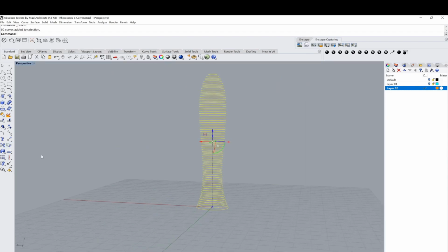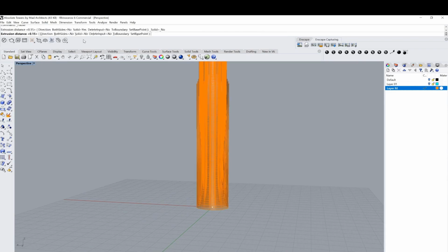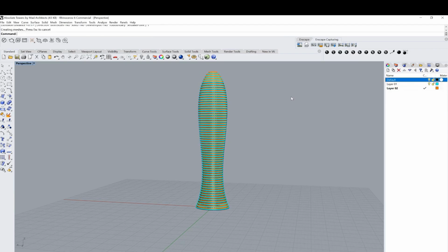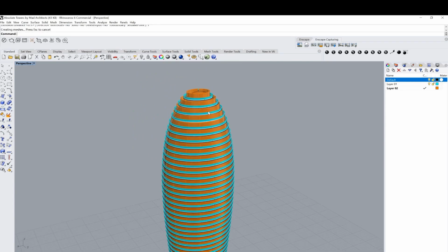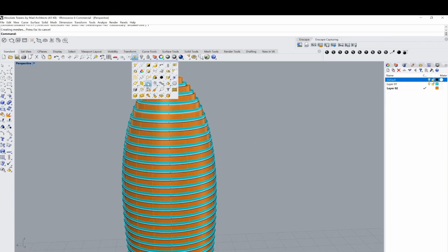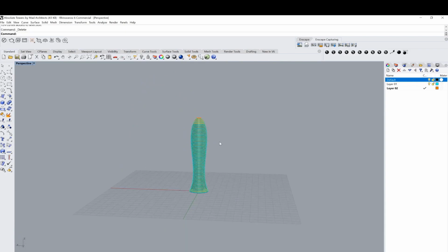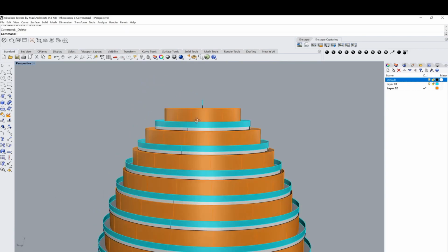And then we extrude curve. Extrude straight. Check your solid option is off because we are only creating our glazing, right? Not solid forms. So solid off and 1 for each floor. Press enter. Show all of our surfaces. Then we choose all lines, select all of your curves, and delete them. Cool, we made our building.